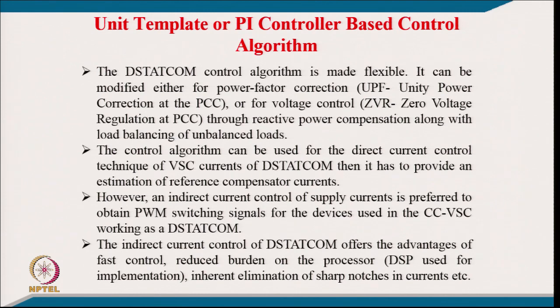The D-STATCOM control algorithm is made flexible and can be modified either for unity power factor correction at the PCC, that is one requirement, or, as we discussed earlier, for voltage regulation, for zero voltage regulation through reactive power compensation along with load balancing of unbalanced load. So, with the help of reactive power you can achieve either power factor correction to unity or zero voltage regulation. The control algorithm should be modified accordingly.